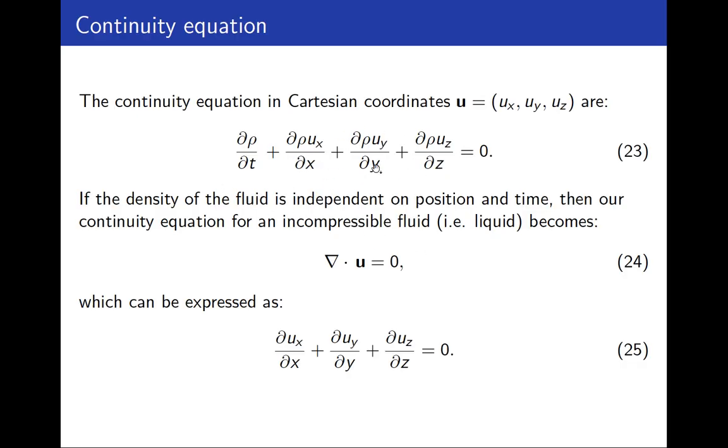We can simplify this equation further. If the density of the fluid is independent of position and time, then we have the continuity equation for an incompressible fluid, that means a liquid, where we do not observe changes in density.